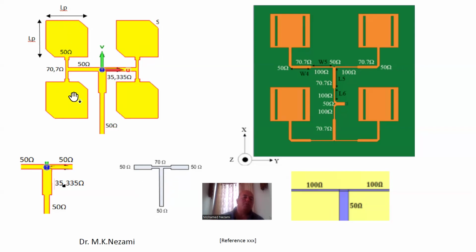Of course, it's a mirror image, so whatever you do to these two, you're doing on these two. This one here is a little bit different. This one actually uses this one here as well. So we come in 50, and then they use 200 ohm lines, okay? And of course, a 100 ohm line, that's probably the max, the highest impedance that you would want to use on the antenna feed networks, because this line is very thin. So depending on the substrate, it could be as low as 5 mils to do a 100 ohm line.